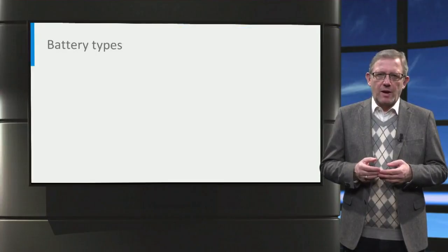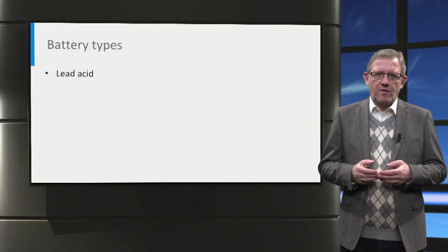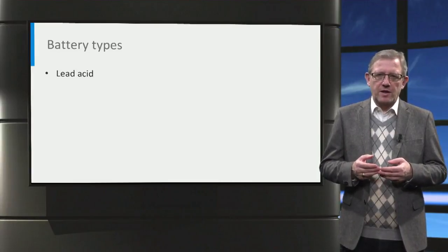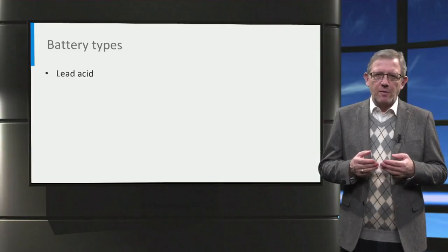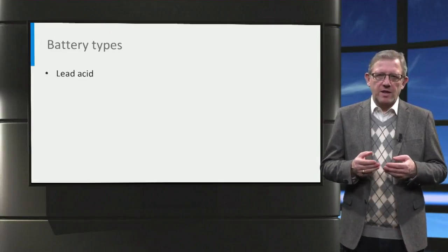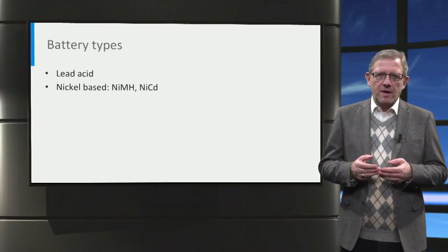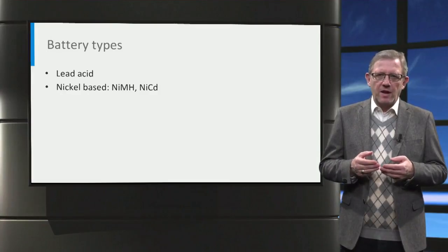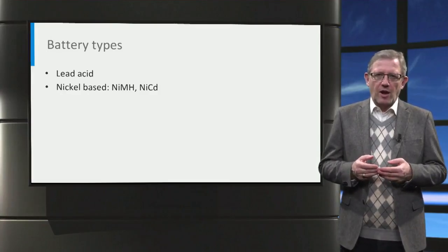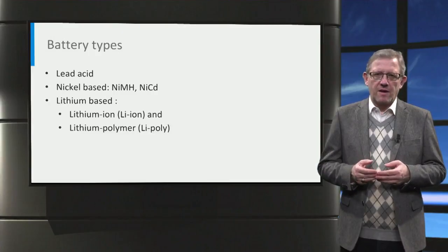Let us now look at the battery technologies that have been applied to electric cars. First is the lead-acid battery. The prospects for the use of lead-acid batteries in electric vehicles are limited due to the low energy densities, sensitivity to temperature, and life cycle. Next is the nickel-metal hydride batteries. They have been extensively used for traction purposes and are optimized for high energy content.